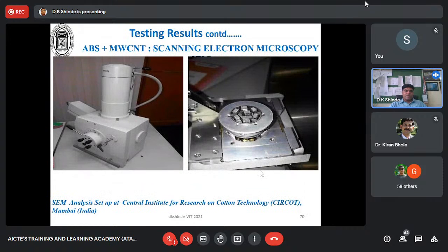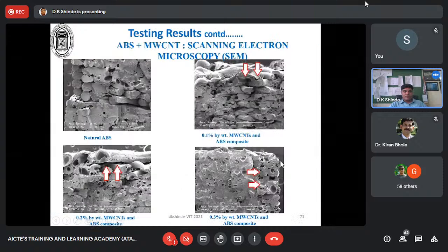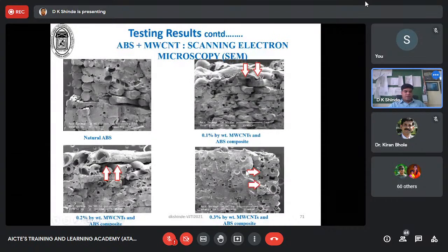We also did the SEM analysis to understand what the air pockets are and where the bonds have not been developed properly. There may be chances of reduced properties, maybe in flexural, because of such air pockets and because the material is not properly cured also. So curing has to be addressed in the 3D printing so as to avoid more and more such defects.